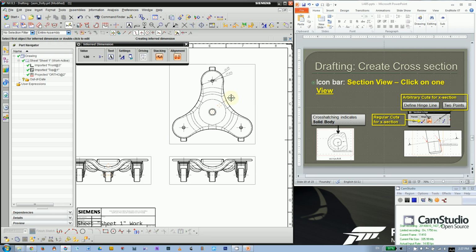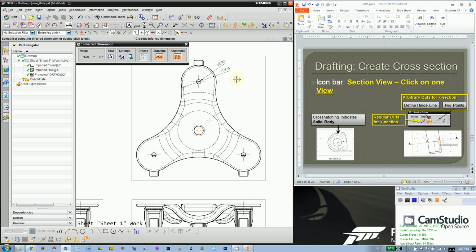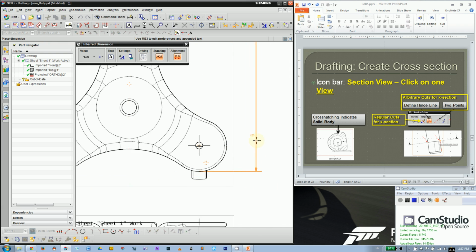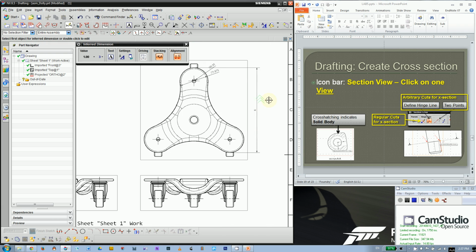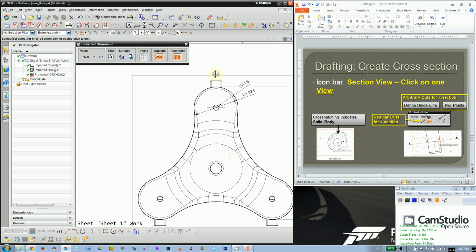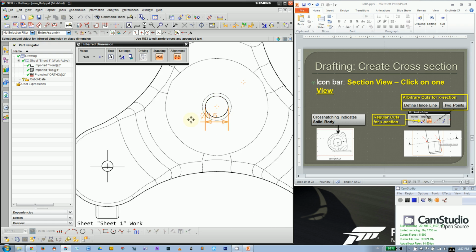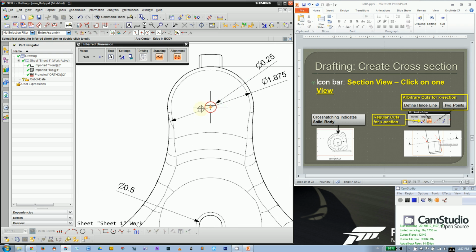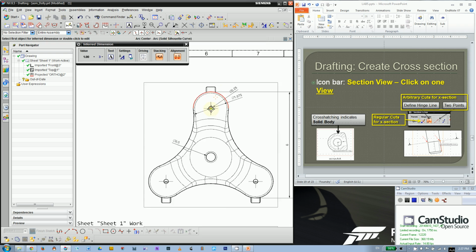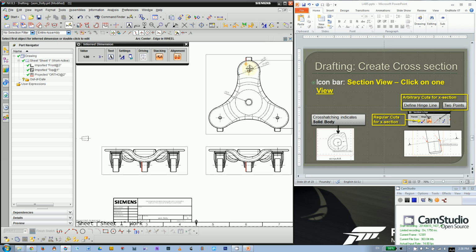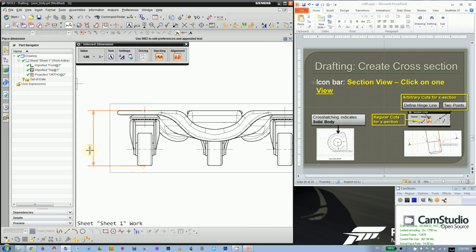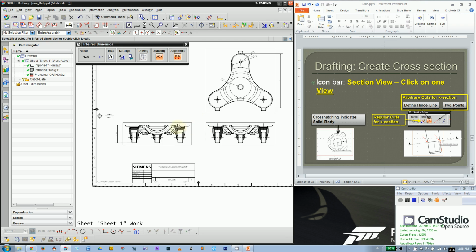And for assembly, your dimensions don't have to be so detailed as an individual part. So usually we need a total length, total width. So that's how tall this thing will be, in total. And it's like a footstep of this. Then you might want to show some hole dimensions. So the assembly dimension, like this hole will be a 1/4 inch in diameter. That means your rivets, your nut should be a 1/4 inch, and the total height. Okay, so this is how you put in dimensions.